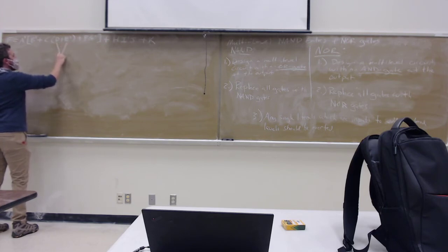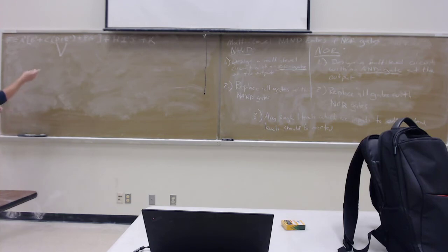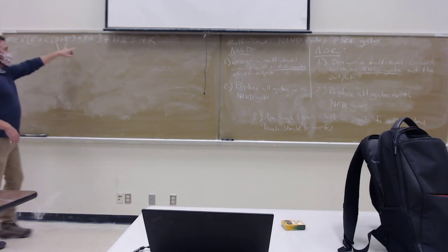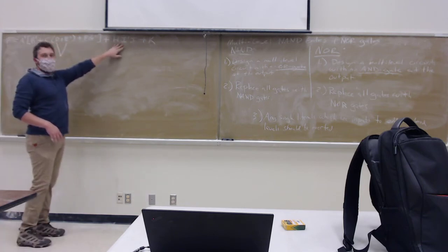Because there's one big rule, right? We talked about it. We said we might break it from time to time, but there's one major rule that says all the levels have to consist of the same gates, right? So that means when you're thinking about the levels, what gave me pause is, well, we had D or E prime, because that's dependent on C, and that feeds into this next one, which feeds into all these guys, but we could have done this AND gate level first, right?